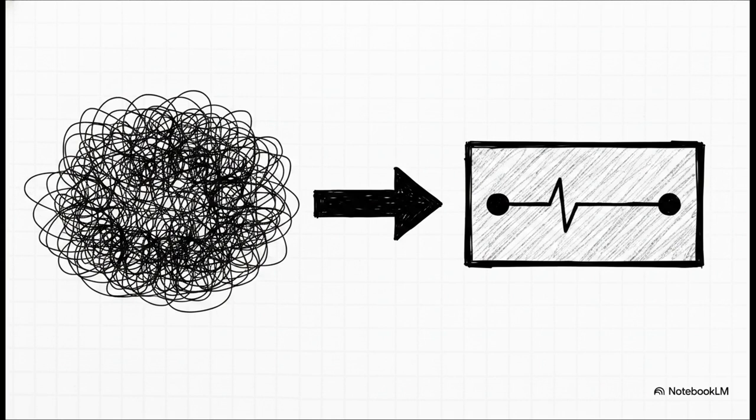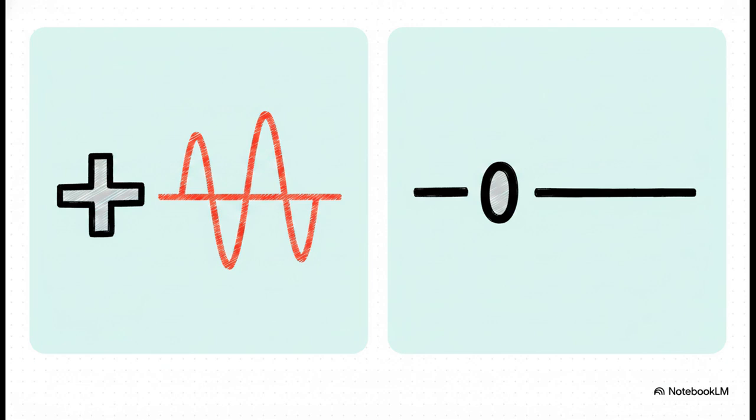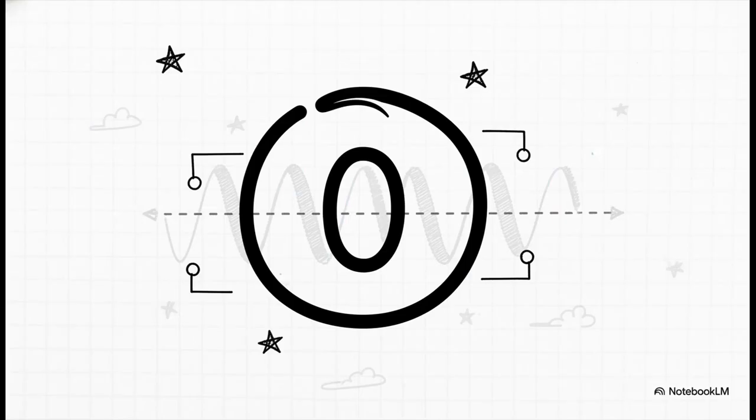It's pure genius. And this brilliantly illustrates the stark contrast between our networks. For the positive network, the Thevenin voltage is the actual pre-fault open circuit voltage. But for the negative and zero networks, their Thevenin voltage is completely different. Let me emphasize this because it is absolutely crucial data. The Thevenin voltage for both negative and zero sequences is exactly zero in a balanced system. Why? Because those negative and zero sequence voltages simply do not exist when the grid is in its normal, perfectly balanced pre-fault state. They're basically mathematical ghosts, right? They only materialize when things break down.